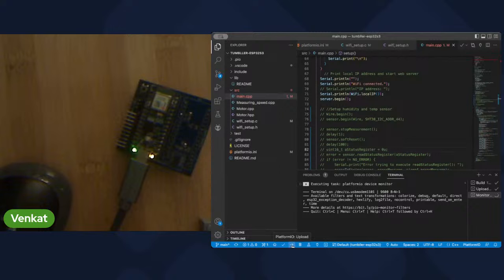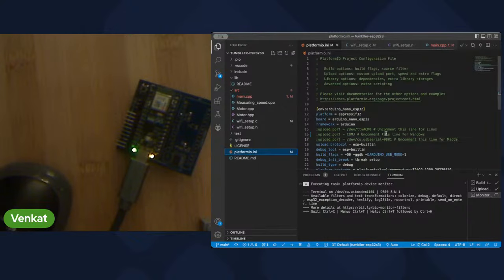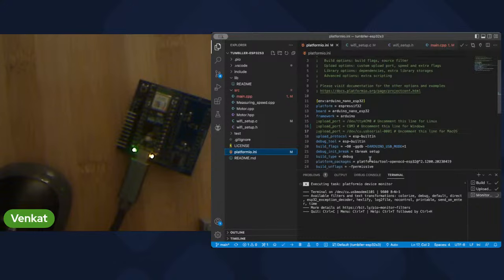There's a green flash, and I don't know what happened now, but is that a baud rate problem? There's some 9600 there. Last time you wanted it 115200, so I don't know how to change it here. Okay. You can set it in platformio.ini. Somewhere. Oh, what was it?